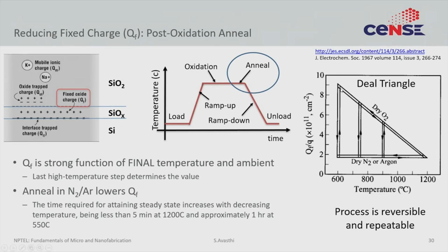First, as you increase the temperature while keeping the wafer under dry oxidation, the defect density falls. So, as much as possible, try to grow your oxide at higher temperatures instead of at lower temperatures.